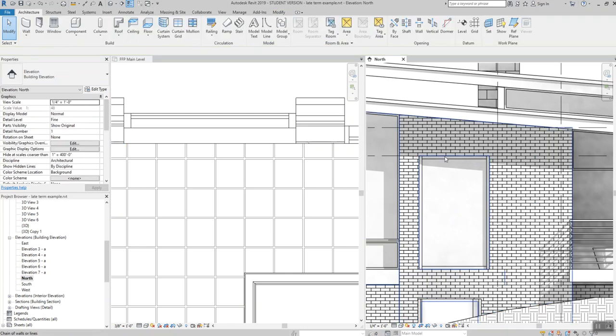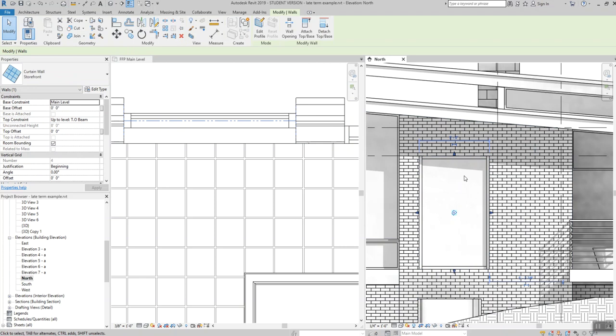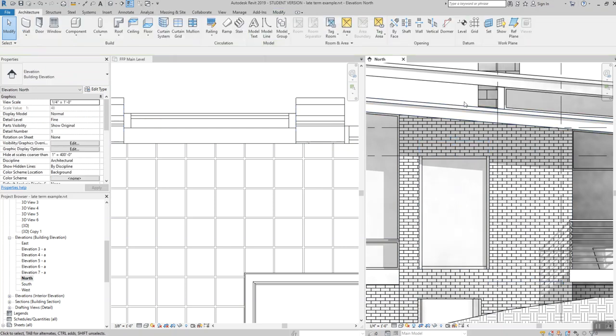So I want to tab, and it says walls, curtain wall, storefront. That's going to pick the whole system. Click. Okay. With that selected, and I just want to say this, if you don't have that piece of storefront selected, then this won't work. The option to edit the profile will not appear. Okay. So if I hit escape right now, escape, you see that edit profile goes away.